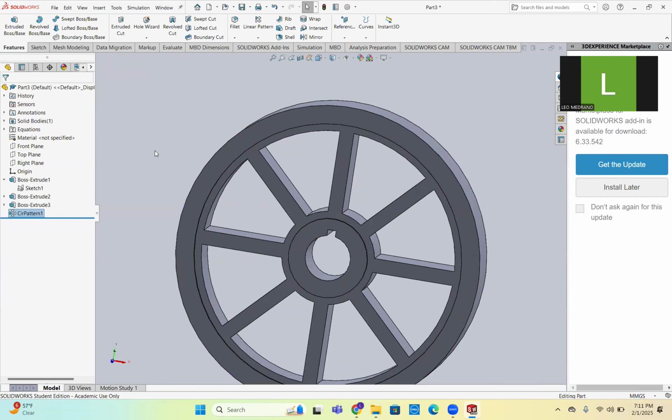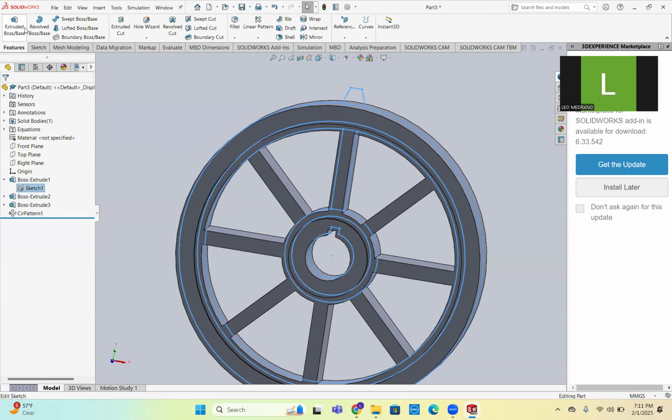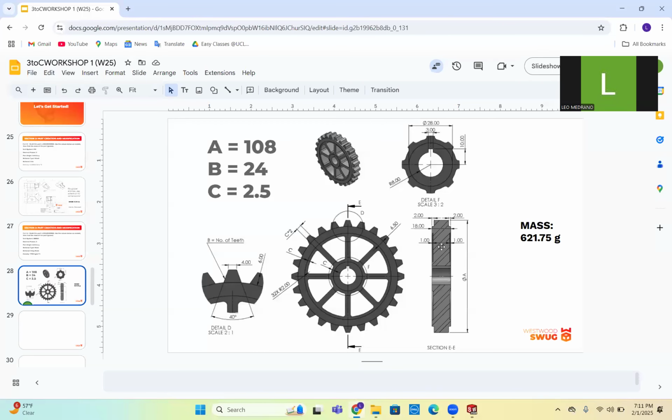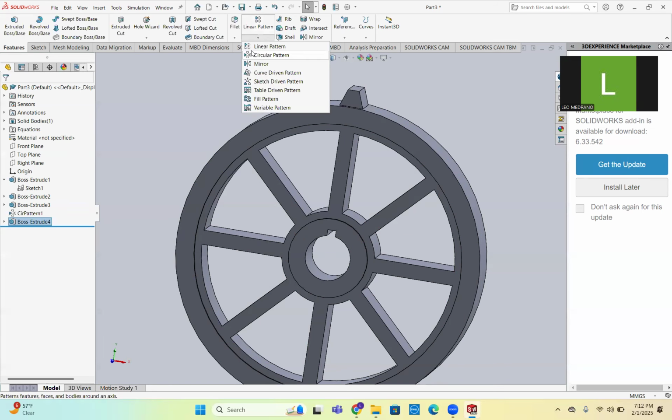So the reason why, like I mentioned earlier, between circular sketch and regular circular pattern, by first extruding the pillar and then doing the pattern, it saves time by not having to figure out the dimensions. So last thing we have to do is we'll go hit the sketch, extrude boss base, is the teeth, and we know that that's 14 because it tells us that it's two each. Awesome. So we'll hit here, change this to 14. Awesome. Hit the tooth, hit check here, circular pattern.